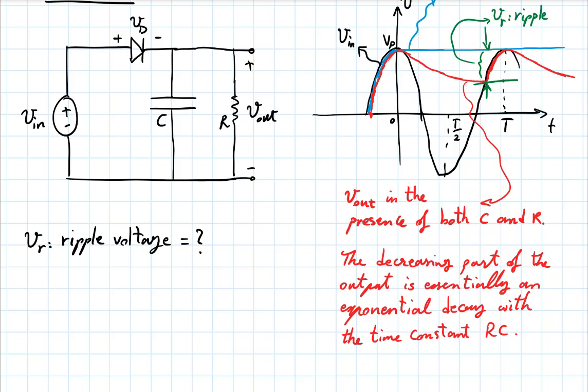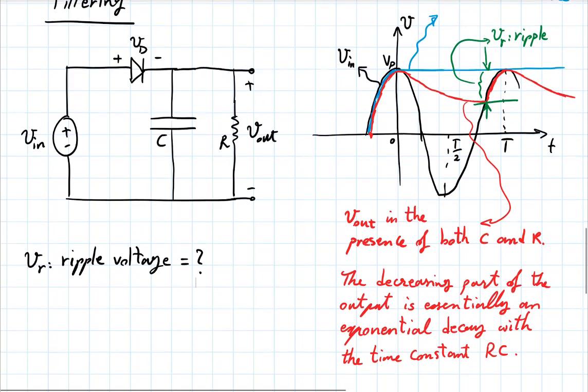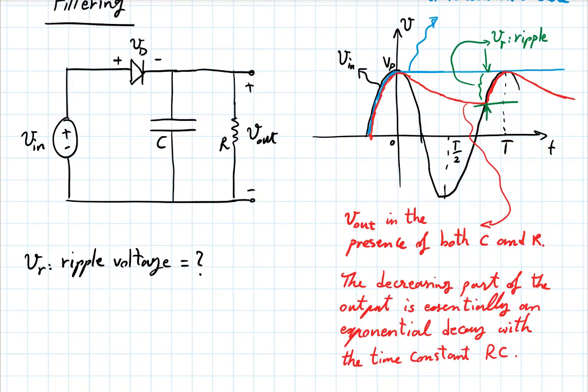Now you're an engineer. How would you calculate it as an engineer? Let's think about a good approximation. If this is going to be a good power supply, you want a small amount of ripple, right? You don't want a big drop. If the peak is 5 volts and the ripple is 4 volts, this is not really doing its job, right? It's a nice circuit question maybe, but it's not a power supply. So if the peak is 5 volts, I wouldn't want anything that has a ripple of more than, let's say, 0.5 volts, right? 10%, or even much less than that, okay?